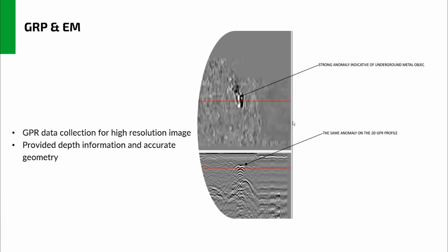While on top of it, you can see some sort of, not U-shaped, but almost like a wide V-shaped layer, which we think is from the original excavation. And this is one of the beautiful things about GPR, that it can actually see unexpected results or changes in the subsurface, even probably after decades when they happen.